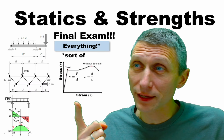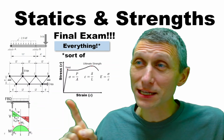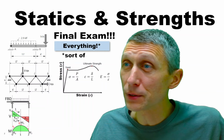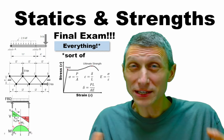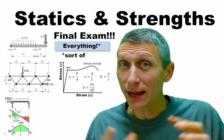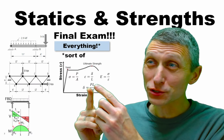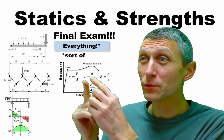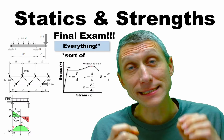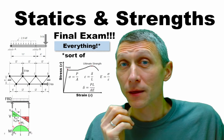And also when we start to look at things, we get strain, change in length over length. We get the modulus of elasticity, which is the slope of this line here. These types of things can all get put together in something like axial deformation. Now, when we start looking at strength of materials, these equations become key. I was just teaching a concrete design course, and we were talking about how from strain we get stress, and from stress we get force, and from force we can figure out member capacities. These concepts all go together because they help you design better structures.